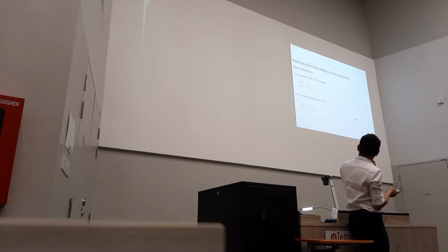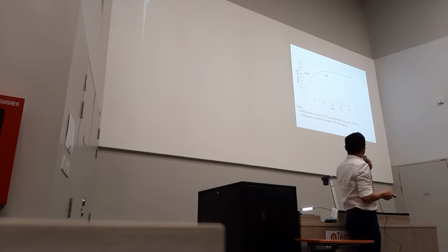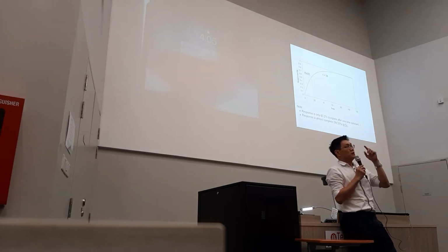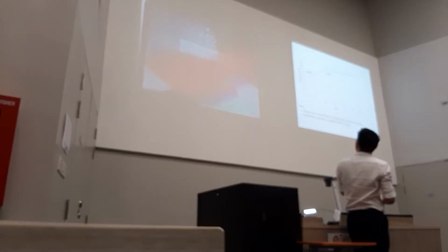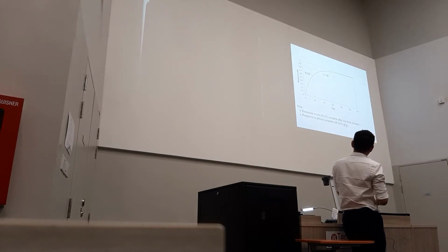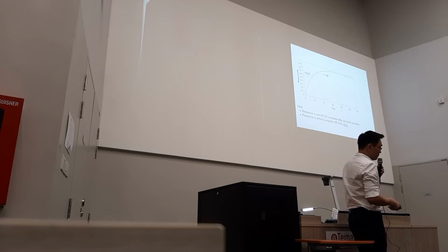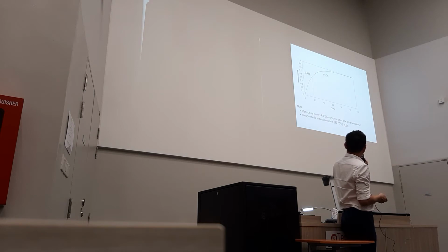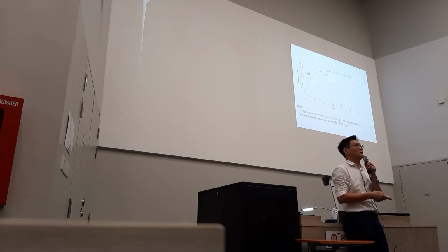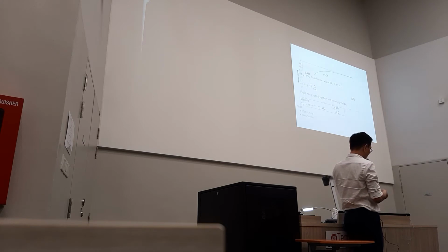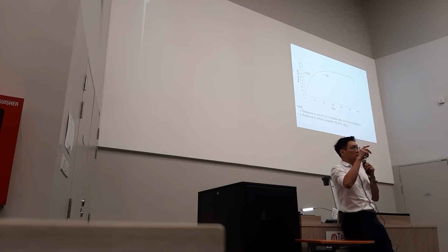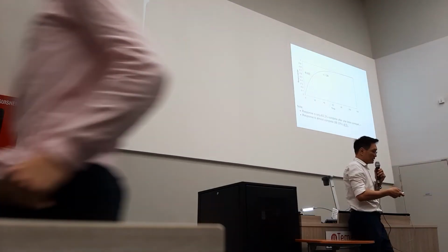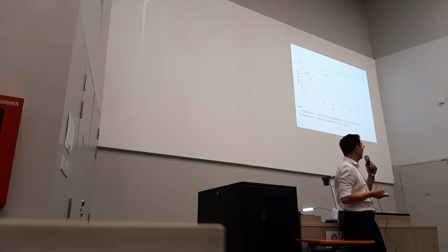Then each of these has a different response. Remember this is the first order transfer function when we have a step disturbance. The curve looks like an exponential, which means that eventually the response will go to a final level. The bigger the tau, the more sluggish the process. Remember I had 1 tau, 2 tau, 3 tau. The bigger the time constant, the slower the process, which means the process dynamic is slower, okay?